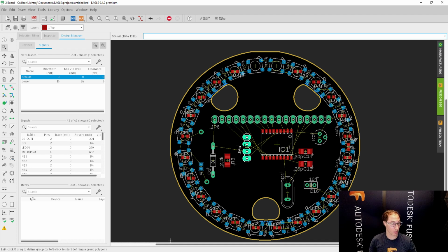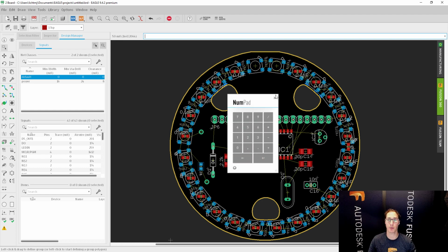And instead of having to worry about that, let's actually switch back over to this camera. There we go. Instead of having to worry about that, I can do my best job as the electrical engineer here and then fix everything in Fusion where you can see all of the visuals of the 3D models. Remember that the electronic components, they have a thickness as well, right? There's a height to all of them. And I don't see that in Eagle either. All I see is a 2D bird's eye view of the layout, not the thickness. So being able to see that in 3D and being able to fix that is a good thing. You're going to want that.